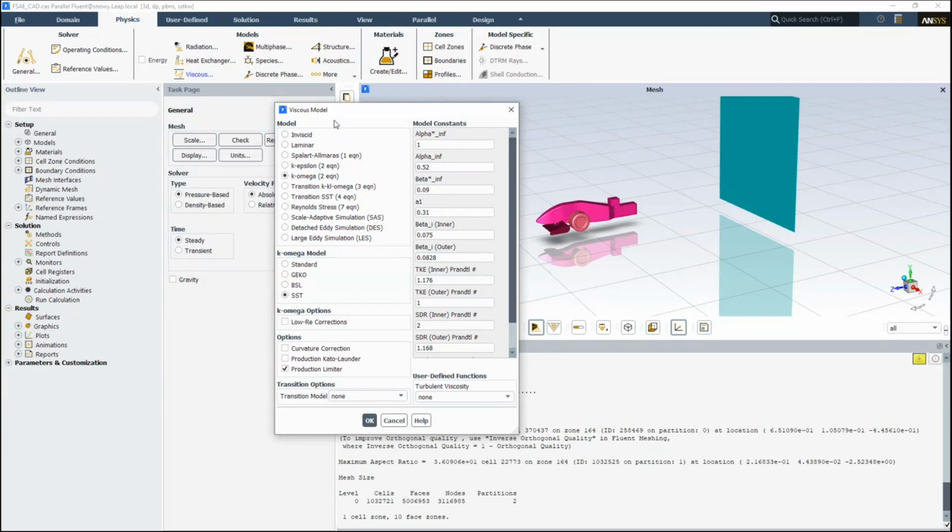I'm going to go through that in a bit, but turbulence, as most of you will understand, is a chaotic flow phenomenon. So it's really hard to pick up in a simulation, and to actually pick it up properly, you need a really, really fine mesh. So what we do is we've developed methods of representing turbulence through a bunch of different models.